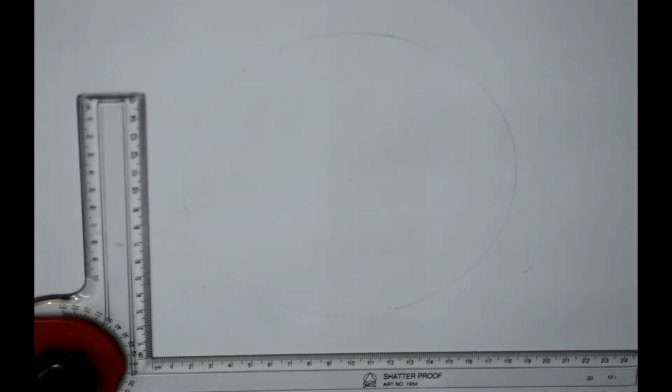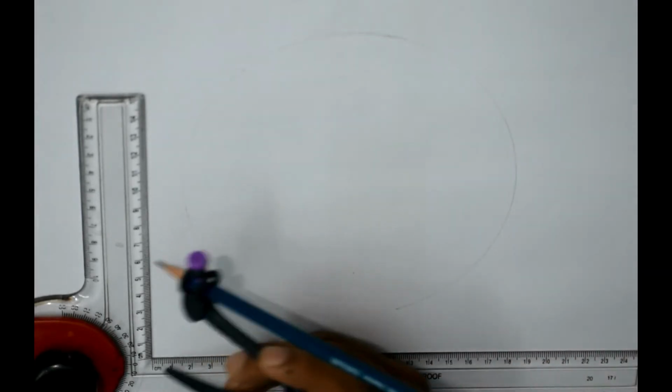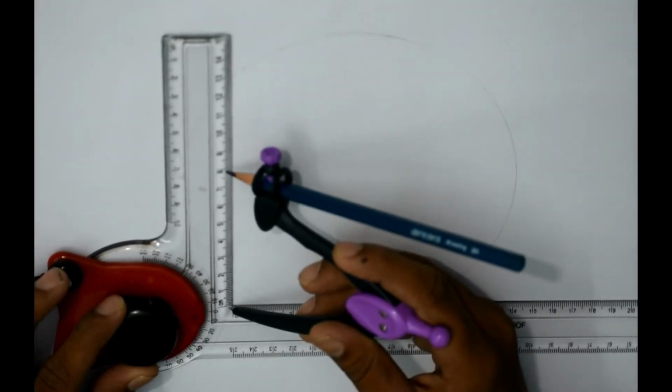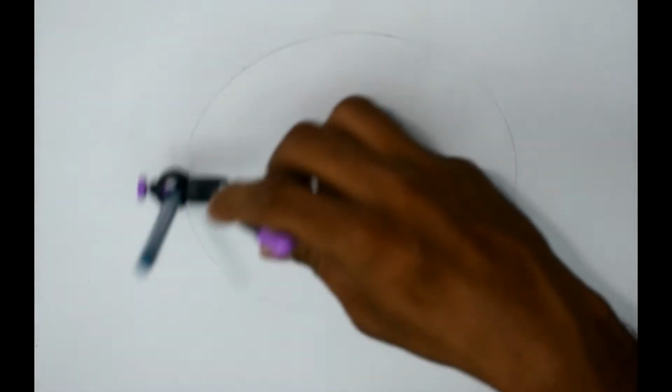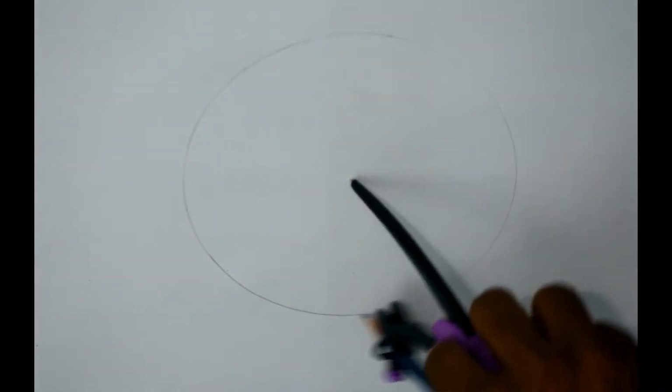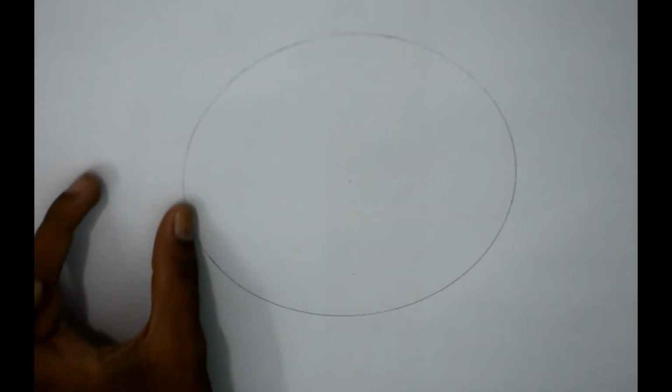So for drawing this hypocycloid, first we have to draw the directing circle which is of diameter 160 mm. So the radius is 80 mm. I have already drawn the circle with 80 mm radius, as you can see here. I'll just highlight it one more time. So this is your directing circle, and inside this circle one more circle will be there which will roll inside. Because this is a hypocycloid, the circle will roll inside. The difference is that in the epicycloid, you have seen that the circle was rolling above.